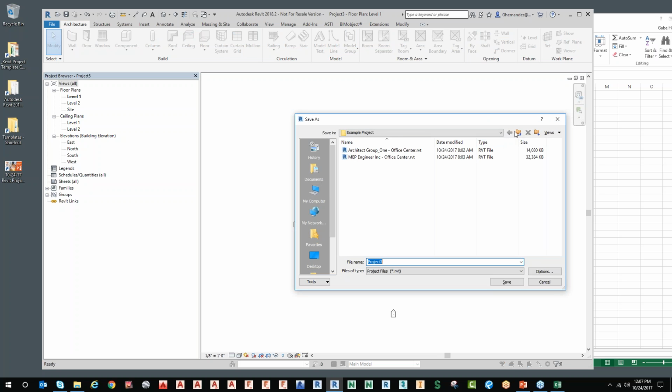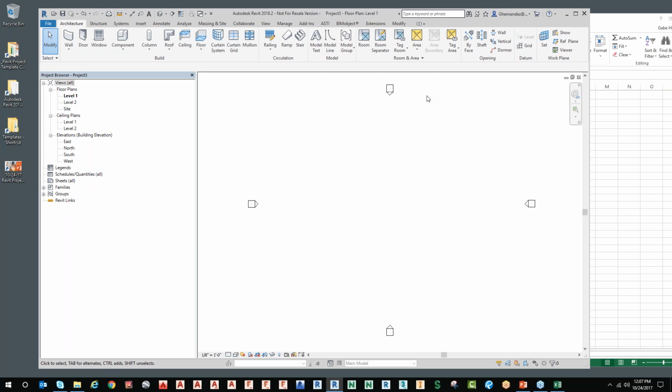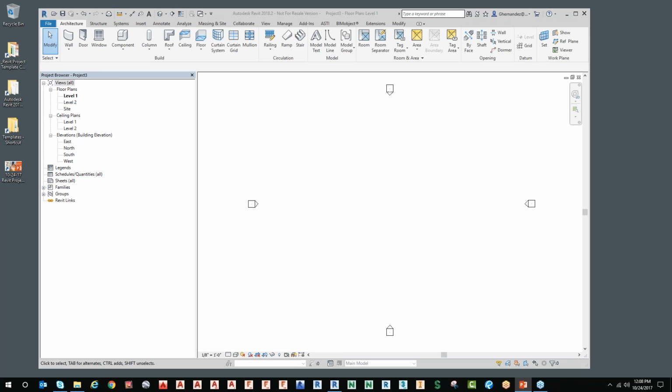project, and this would be called template with work sets, right? That's what I would use to create or have preloaded work sets in a template file. And then every user that starts this project would take this template with work sets and save as the new project and then get started with their process, right? So again, there's a couple of different ways of doing the exact same thing. That's kind of a workaround. Now let's see, what else?